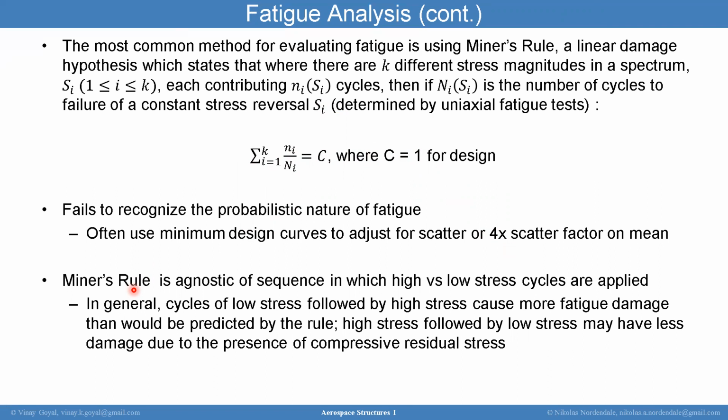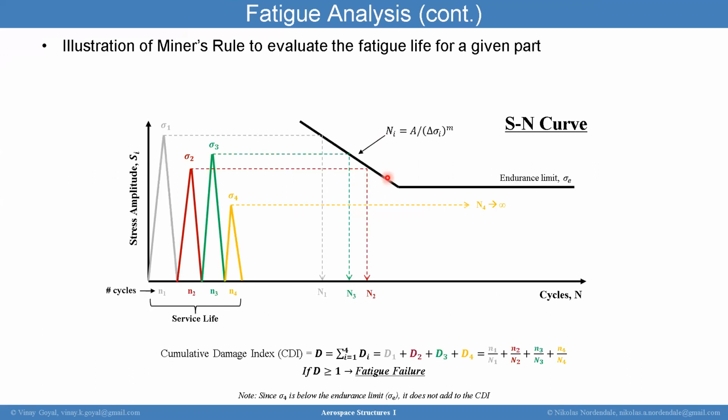And high stress followed by low stress may have less damage due to the presence of compressive residual stresses. So I advise you to then use the approach that gives you the highest cumulative damage index in the calculations.